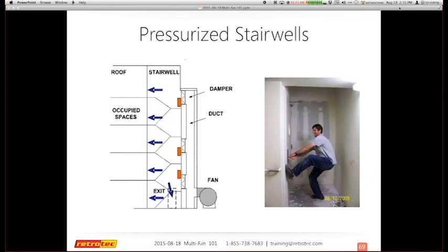Sure. Cool. Okay. If you have even one blower door, there are a huge number of extremely profitable tests that you can do. When we do a pressurized stairwell test, we do them for the local utility that has hydro dams and this and that, and they'll put a pressurization system in there. The question is, how much flow do I need? They have no idea. 10,000, 5,000 CFM, whatever. So I come along with my blower door, I turn it up to the test pressure that they want, which is usually about 50 pascals or so. Sometimes it's 25. And I say, you need 2,500 CFM. They say thank you very much, and that's what they buy and install, and everything is fine.